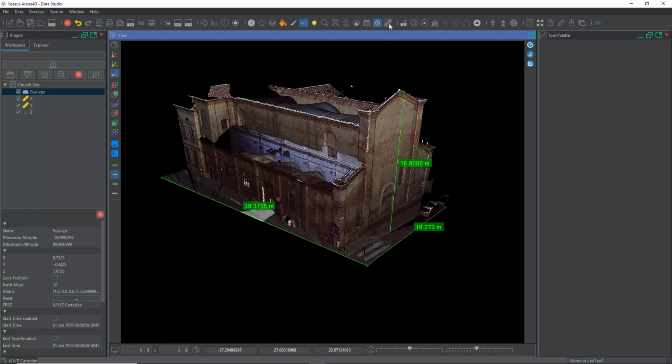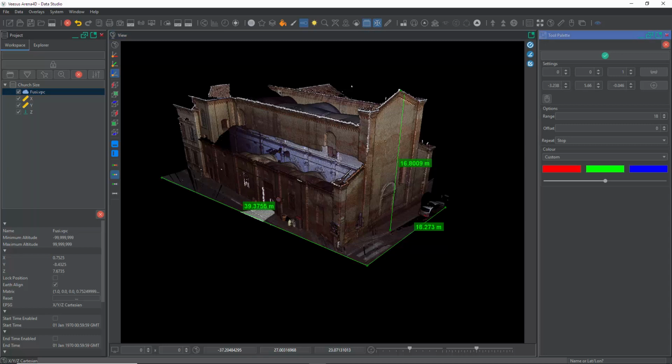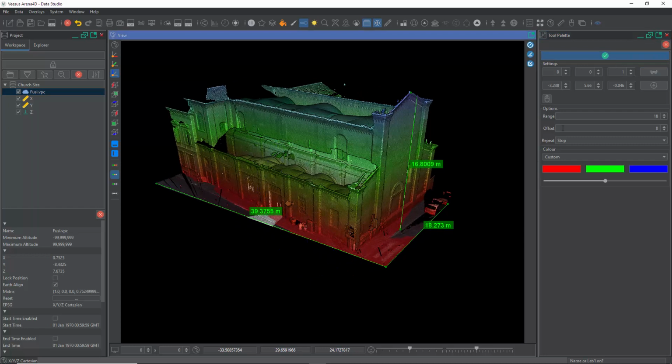So first thing I'm going to do is turn on the shader, and as you can see, here's the options. Now it's currently turned off, so to perform any of these options you just turn the shader on. This stays blue, and I'll just go through some of the settings here. This is the direction, this is X, Y and Z. Currently you can see there's a 1 in Z, which means we're fully working in the Z up direction here. If there was a value on one of these, it could be going diagonally.